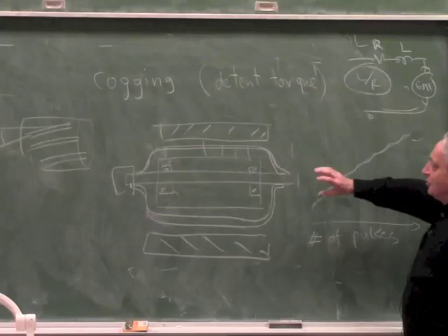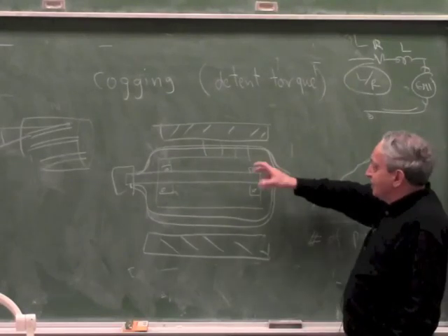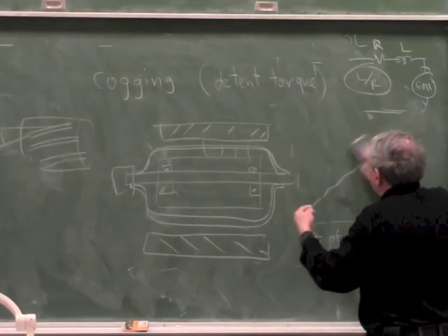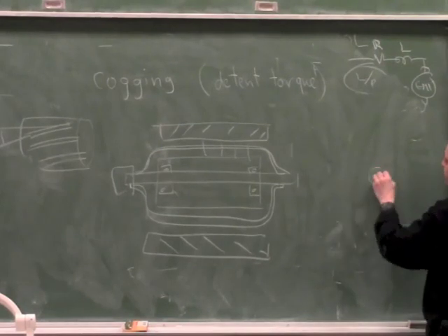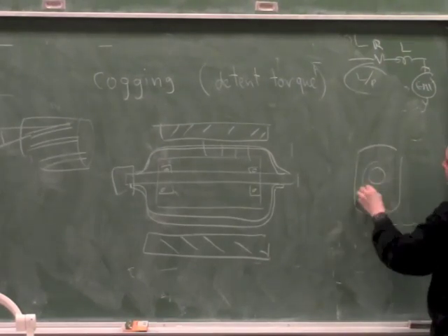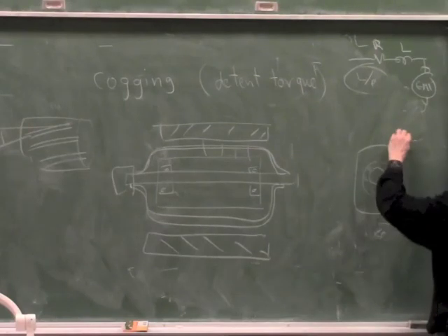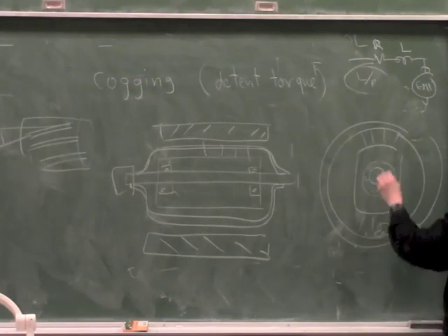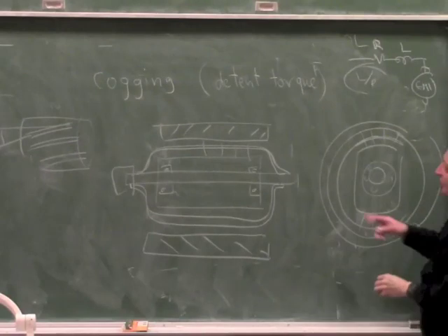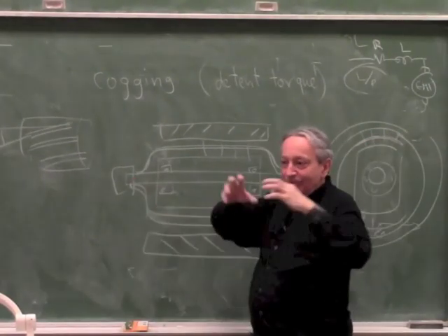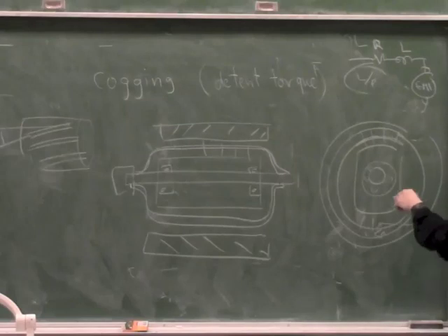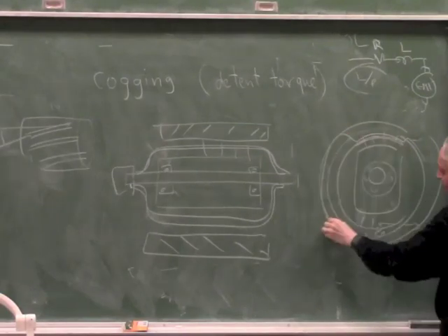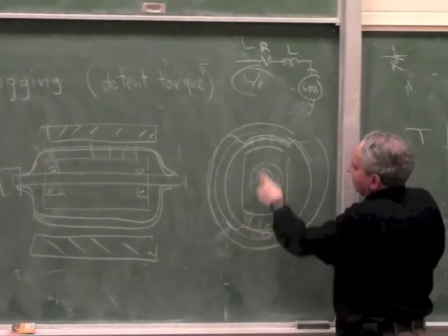So what happens when this motor accelerates, the magnet is free spinning on the shaft. It doesn't have to accelerate. So looking at this motor from the cross-section, you have a shaft, you have a magnet which is sitting on the shaft on a ball bearing, and then you have a ring of steel. Okay, the flux goes like this. The coil is sitting in between, but the coil can be supported in both ends now. So it can be much more rigid, and this can have salient poles. So basically this ring of steel can have salient poles to encourage the magnet to stay in one place.